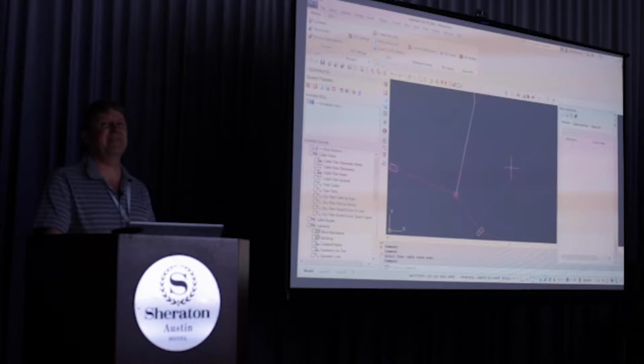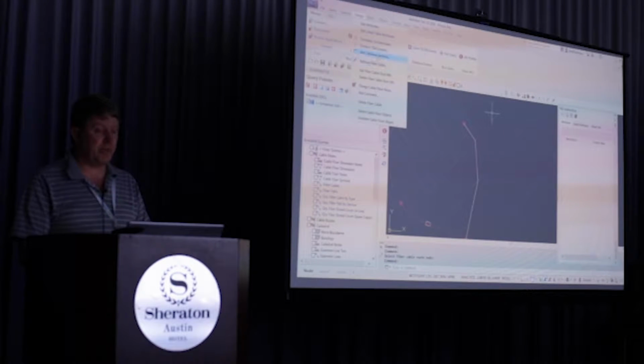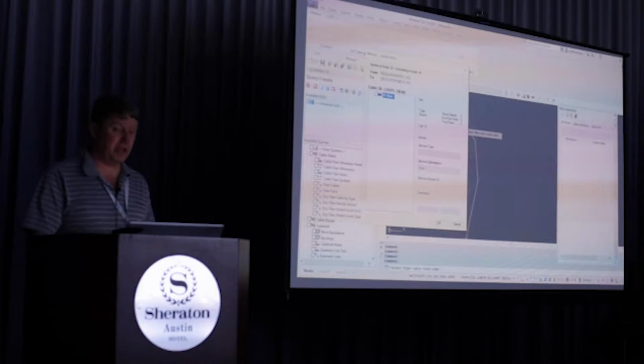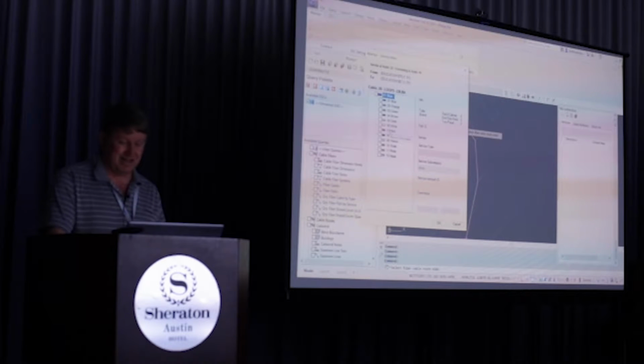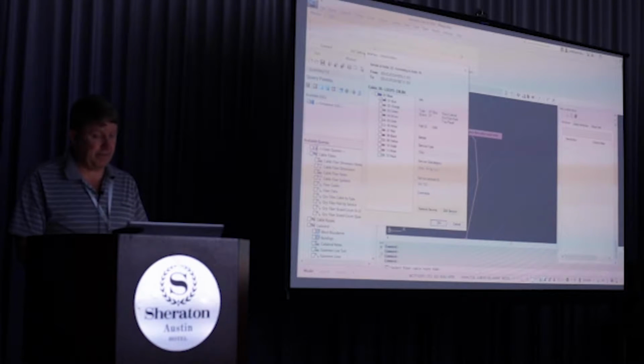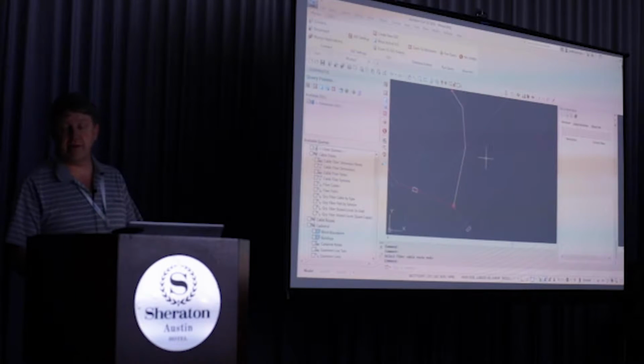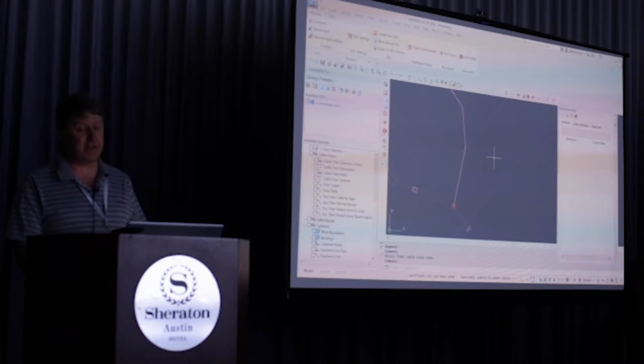Because if you're going to capture a 512 strand cable, you don't really want to go and do 512 individual geometries. So my next step in the process is to say, okay, I'm going to add a service from this location. So there's the 1 tube that we've spliced through, and now I can go and place a service on that. What is the service type? And you can choose categories. So you can go and add services onto the cable, and it's built that connectivity for you. It's a fairly simple process to capture the cable if you know what is going on.